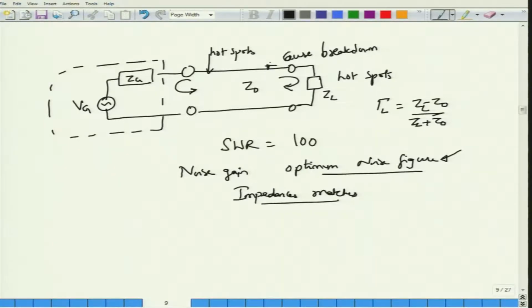So, what exactly is impedance matching? If I go back to this transmission line circuit, you can see that the impedance on the transmission line is Z0, which is not equal to the impedance of the load ZL. So, what you do is put up an extra circuit, usually composed of lossless materials. This network is called a matching network. The objective of the matching network is that if you look into it from left to right at this plane, the impedance seen will be equal to Z0.